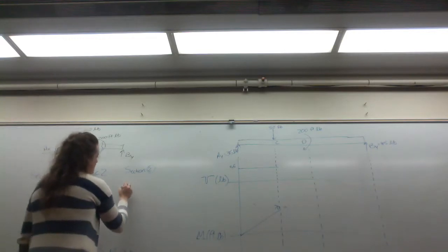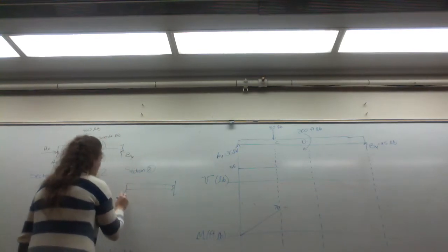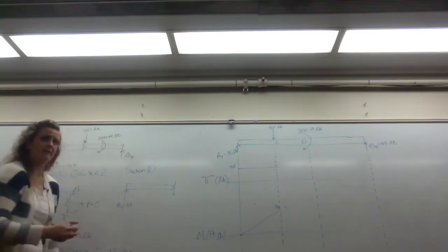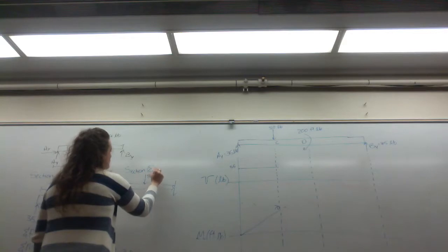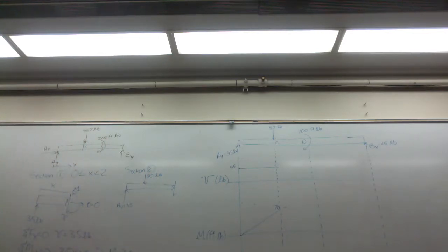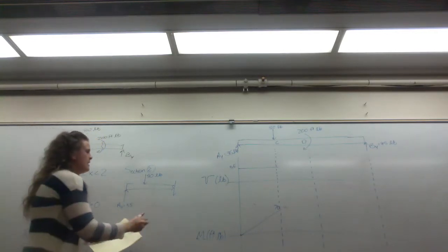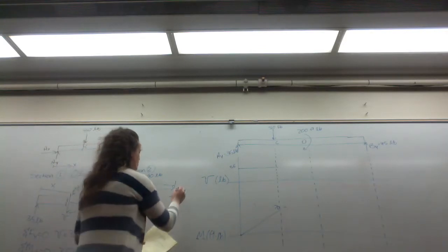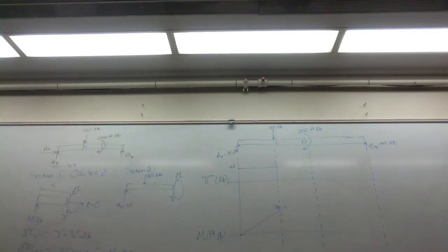So if you draw your free body diagram from A, AY is 35 pounds. We now have our 80-pound external force applied between A and D. So the 80-pound force is there, and we apply our internal forces with our positive sign convention. So shear, right hand side down, bending moment, concave up.